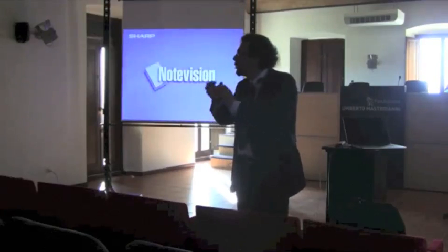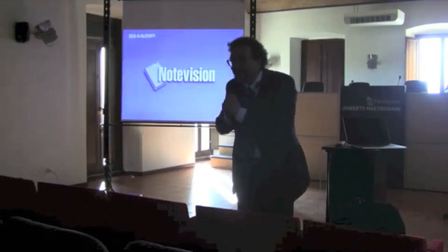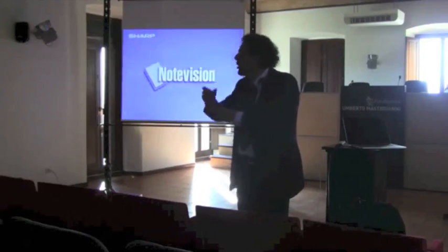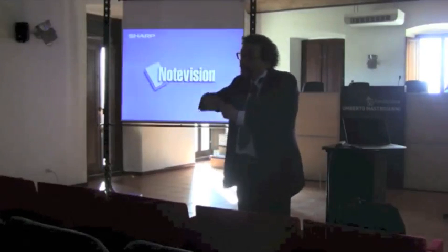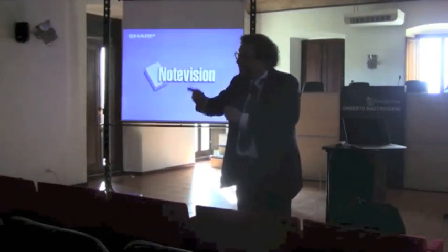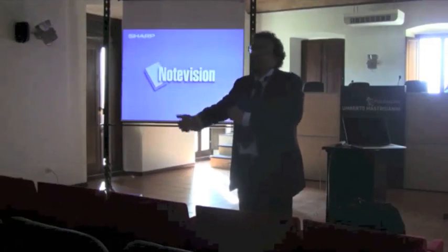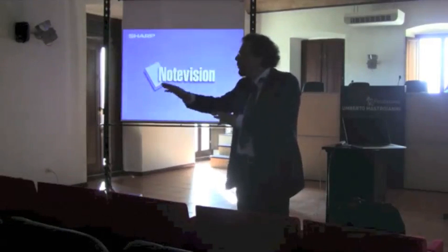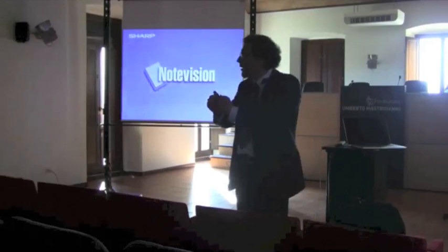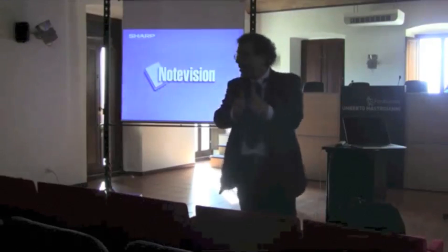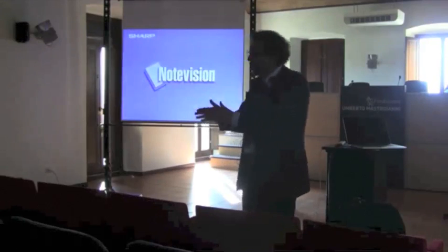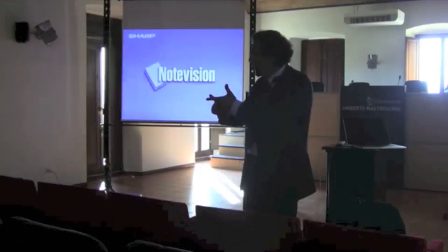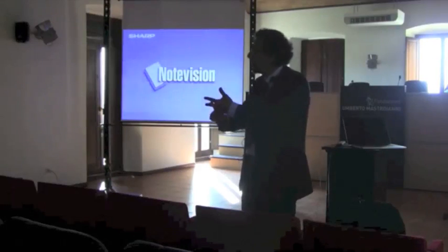However, if you average the micro deformation and you attribute this macro deformation to each elementary couple of grains, you don't find the right energy, because you have some concentrations of energy in some grains. In order to take into account this concentration, you need a kind of micro stretch descriptor which carries one half of the energy, for instance. So I could agree with you that second gradient theory maybe is not the appropriate one here or there. But the message is: write the kinematics, write the energy, and calculate the first variation.